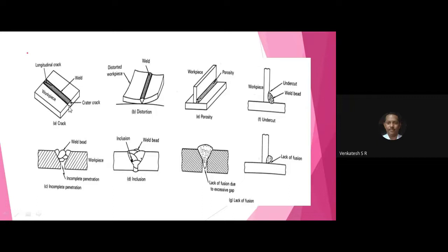See, the crack is formed due to uneven burning of the edges, the welding speed, slow and fast welding, the heat input to the welding, and the type of electrode used in the welding.